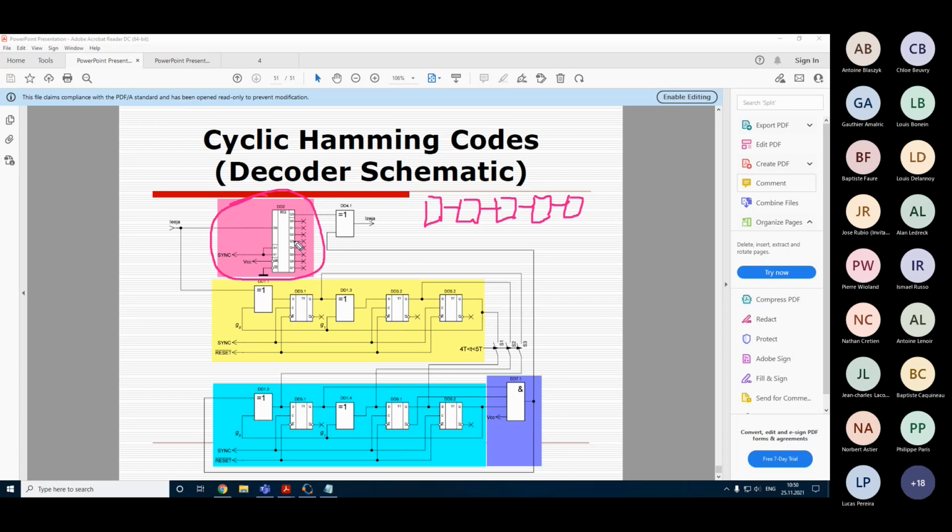Yes, keep in mind that if you have m equal to 31, for example, then you will need 31 flip-flops, or accordingly you can connect 4 such registers in a row. Yes, so here we have the input, here we have multiple outputs. So we need a delay of 7 time intervals.